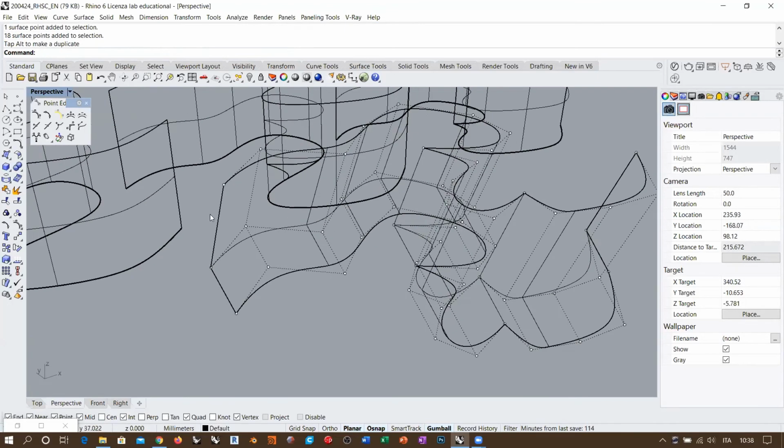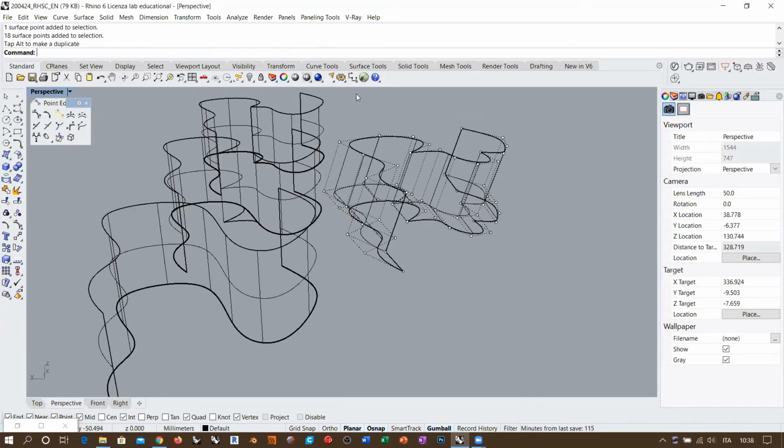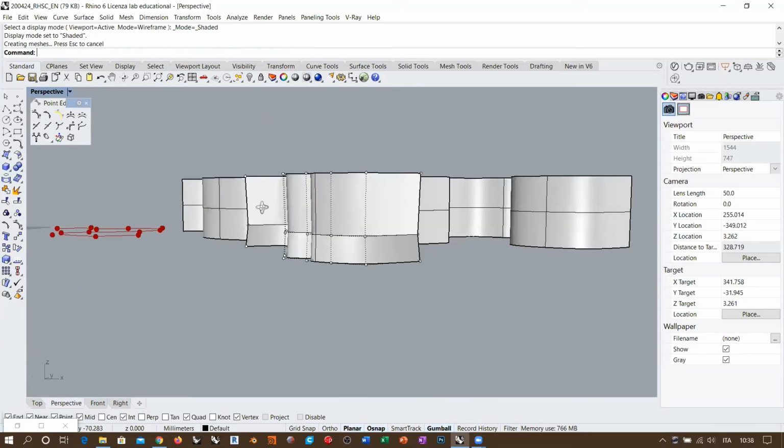As the vertical direction of our surface is linear, the internal kink is actually creating a vertex, which is basically creating a polyline if you think about curves. Okay? So if I move this line of kink points, I don't get a smooth deformation of the surface because it is not degree 3, but I get this kind of internal crease, which also corresponds to a flat or straight connection between the baseline and the top line. Okay, so I get this kind of weird behavior because of the degree of the surface.